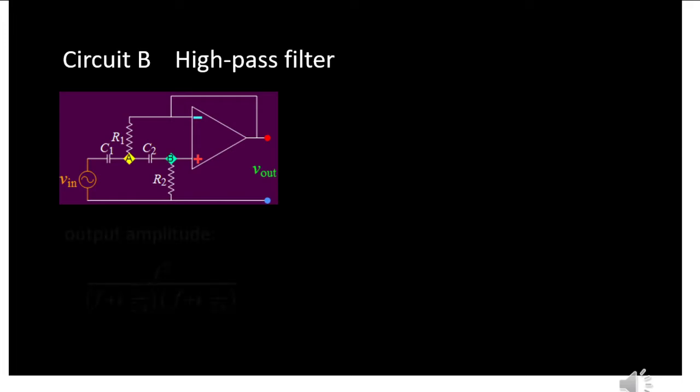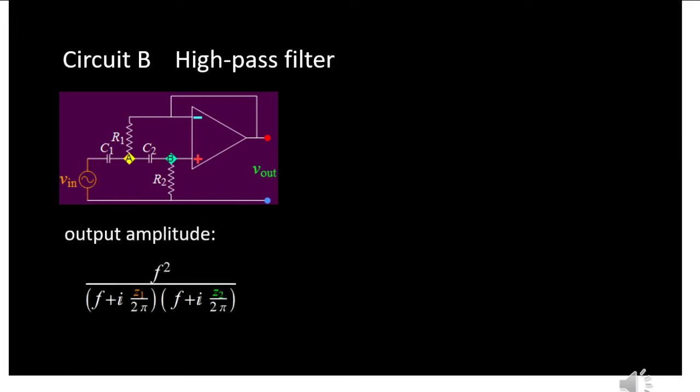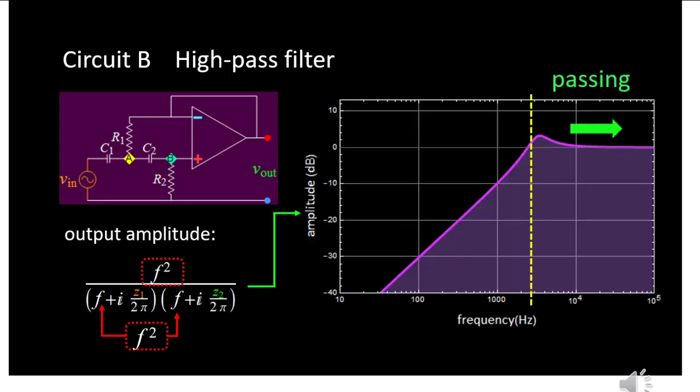In circuit theory, it is called a second-order response circuit, because its response versus frequency scales as the square of frequency. At this point, we need not be concerned with details of the circuit. It is sufficient to say that, given a complex signal, this circuit selects the portions of the signal that have high frequency oscillation, which is above 3 kHz as shown, and greatly attenuates those that are DC or oscillating at low frequency, such as low-frequency noises.